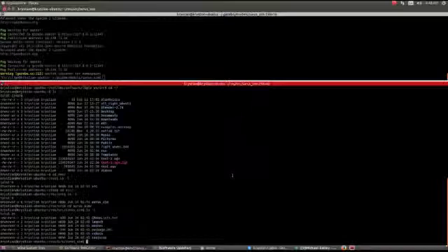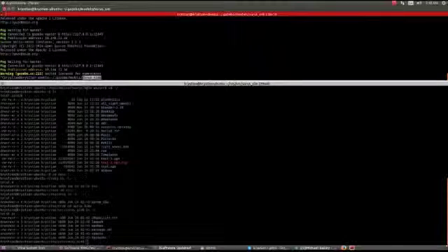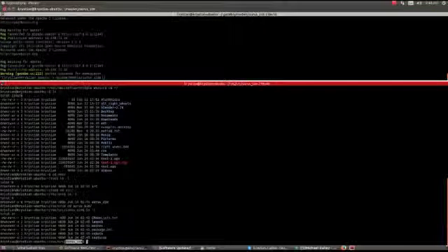Okay, so now that we have pretty much all our joints set up on the robot, and the robot actually can stand by itself now, and the closed loop linkage is complete, what we're going to want to do is actually move the pseudosim folder out of the .gazebo models folder, which is right here, and move this folder back into the folder that we created for the Catkin Workspace. I would probably remove the pseudosim folder that was there in the Catkin Workspace first, and then copy it over. That way you kind of get a fresh start in the Catkin Workspace.